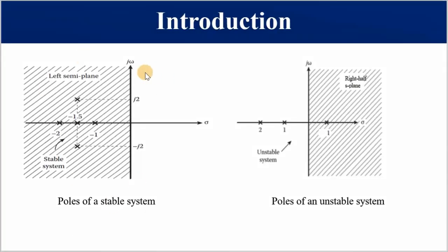This is an S plane, and we've got how many poles? 1, 2, 3, 4, 5. We've got 5 poles. Please, if I didn't emphasize this point, let me do so now. On an S plane, poles are indicated with a cross sign, and zeros are indicated with a 0.